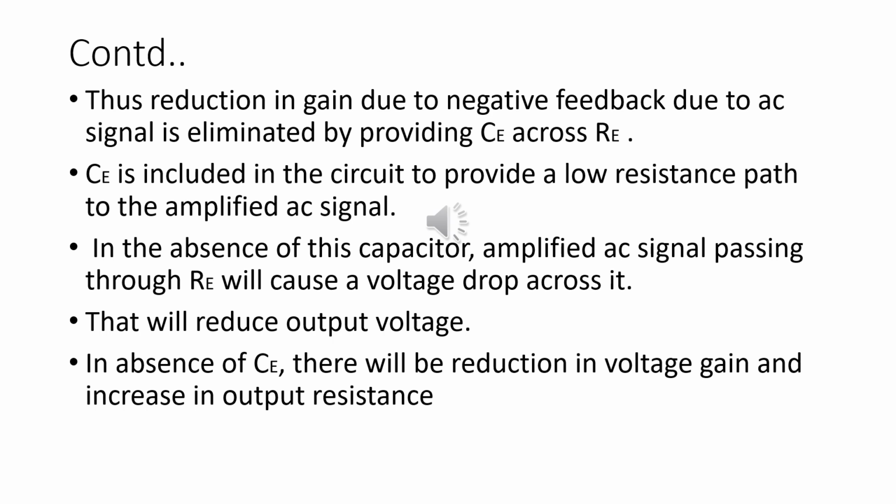Connecting this capacitor Ce, we are providing a short circuit path, or a low resistance path, for the AC signal to flow to the ground. So, we are preventing the voltage drop that may occur across RE, and thus eliminating the reduction in negative feedback and thus increasing the gain of the amplifier.